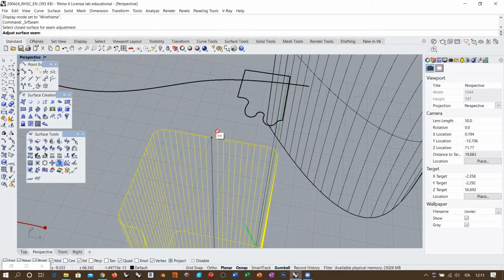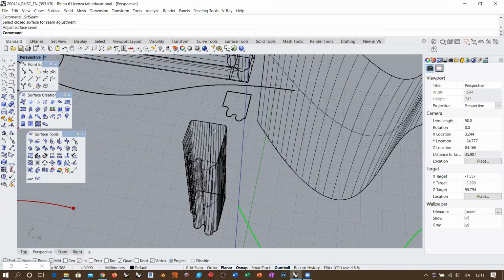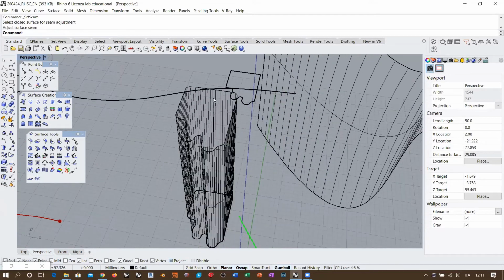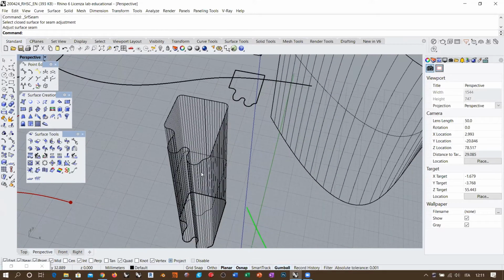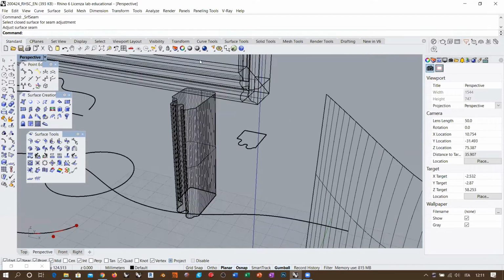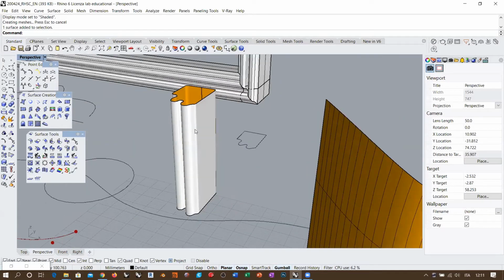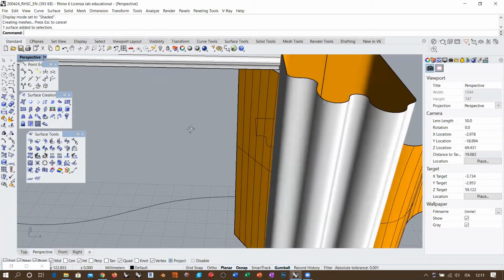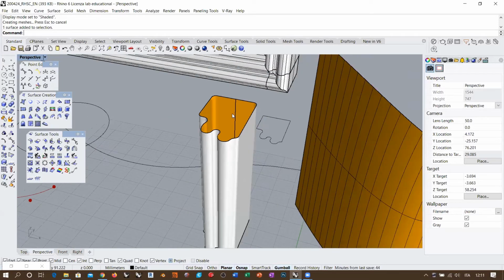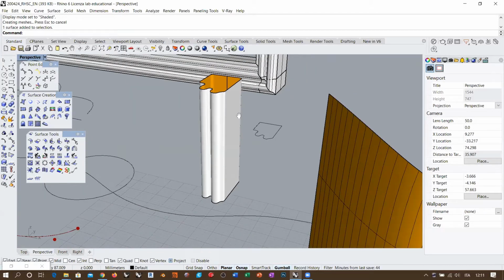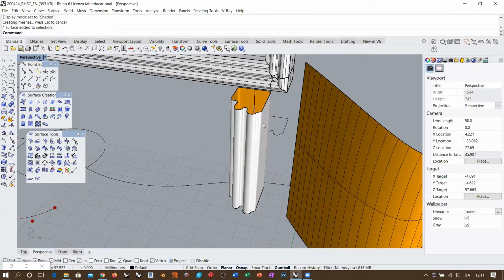Like, for example, I don't know, here. Okay, so you see that I have changed the position of this internal edge, which is now here on the back of my model. Which means that if I hide the isocurves, so isocurve density set to disable, I see a perfectly smooth surface without any internal edges, but this one, which lies in a position that is not disturbing any process.